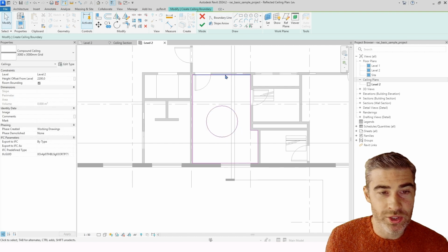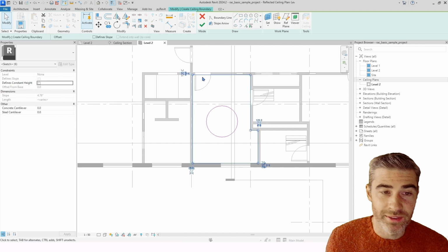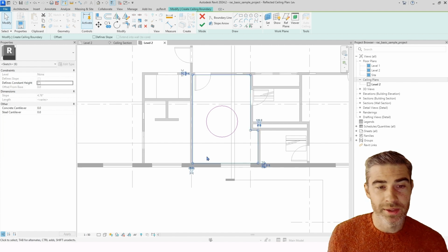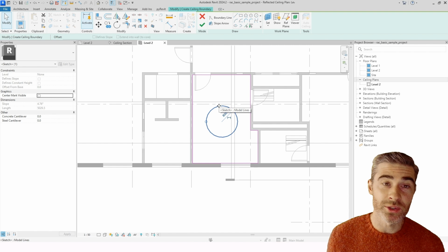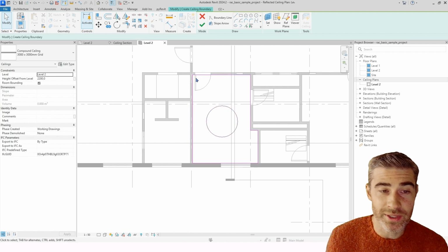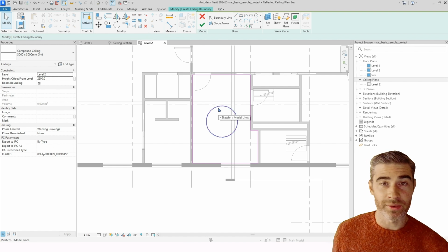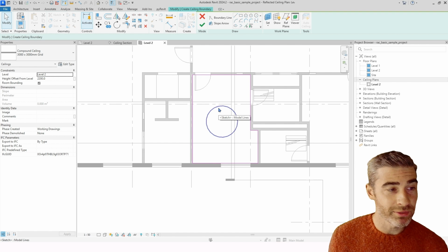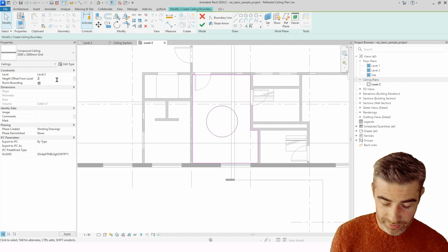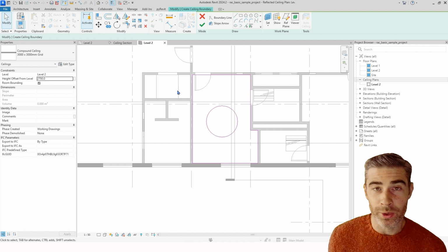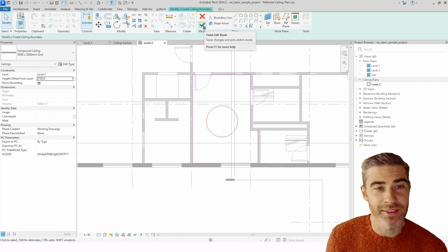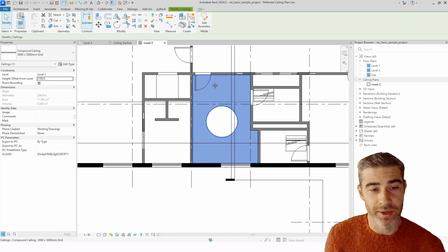So right now, when I select this, this is going to be the extent of our room, and it's allowing for us to either have a drop down or a pop-up, and we'll have to create another ceiling to do so. So once I've got the boundaries created, I've got my design where I think I'm going to want to pop it up created at a certain level height. And again, keeping in mind, we want this at 2700. And that was the value that aligned perfectly to our window in this scenario. And I'm going to hit the check mark to finish our created ceiling.